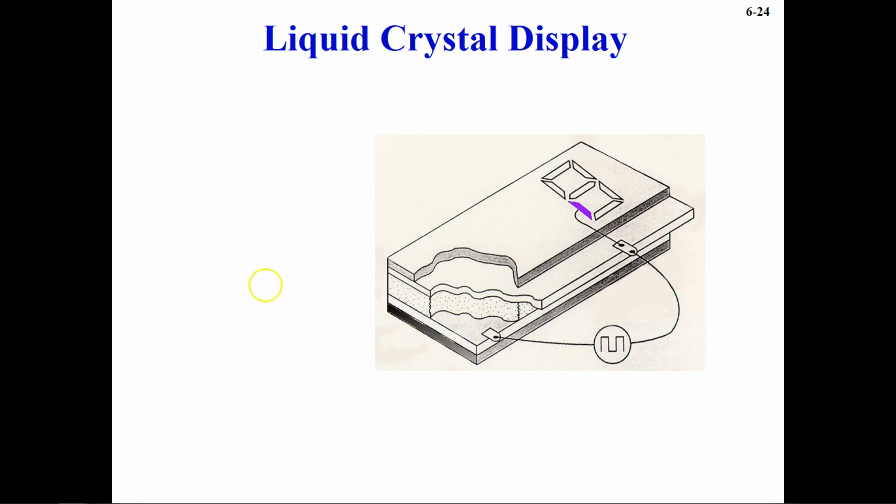So this is a field effect LCD, which you see here. When a segment is energized by a low frequency square wave signal, the LCD segment will appear basically black, while the rest of the surface remains shiny. You can see this segment E, so you know that A, B, C, D, E. This E segment is energized, and the non-energized segments are invisible.